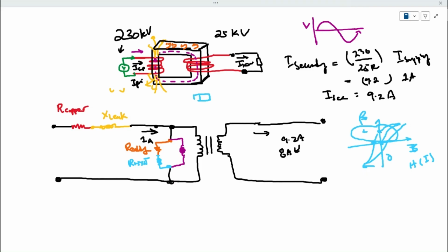So from here to here, for you to flip that dipole to the other way around, it takes some sort of extra energy, and that's called hysteresis losses. Now this gets fairly complicated when you're performing transformer energization studies and whatnot. But right now, let's keep things simple. I just want you to have an idea that there are losses associated with the flipping of the dipoles that are called hysteresis losses.